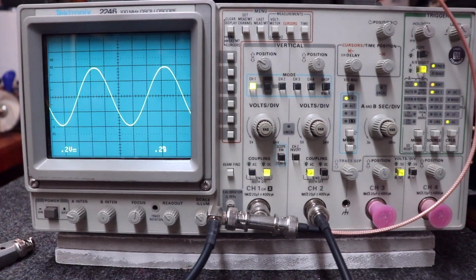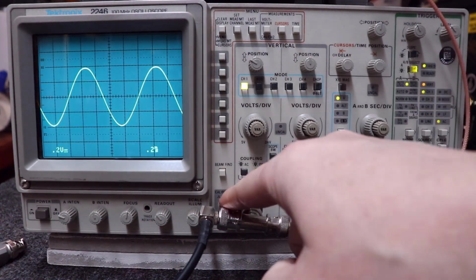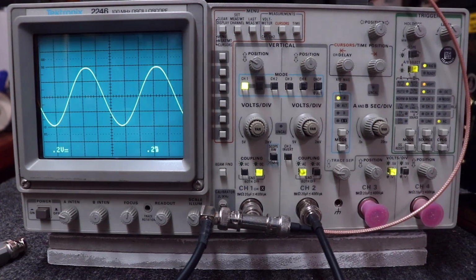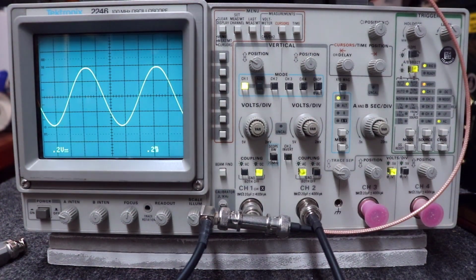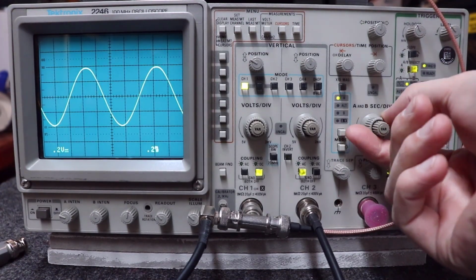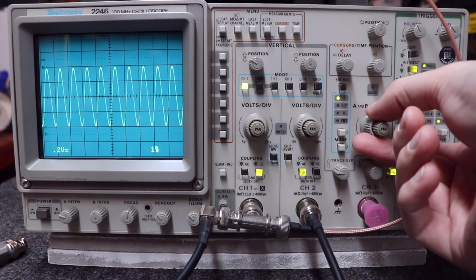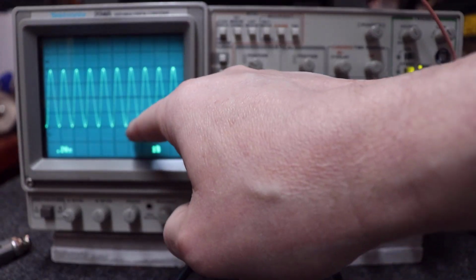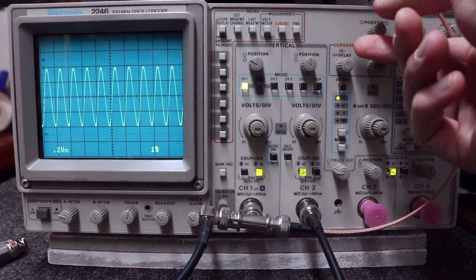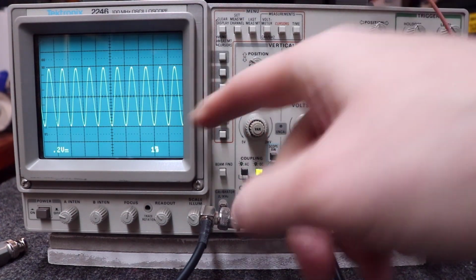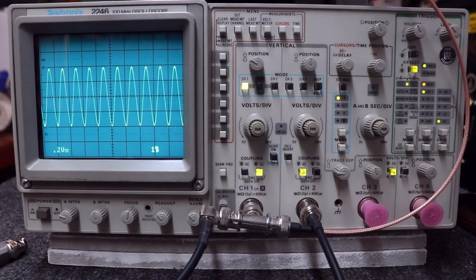All right, check this out. We've already learned the whole vertical section here. Let's get over here into the horizontal section. Horizontal is just that. It's the x-axis, and we're starting to play with time. So if you'll notice, 1 millisecond per little division, and I can shift this using the position button, get it right there on the peak of 1, and you'll notice 1 millisecond between these divisions.